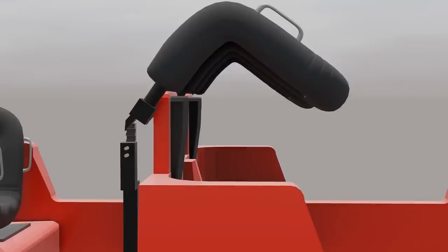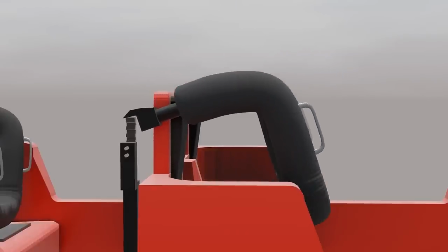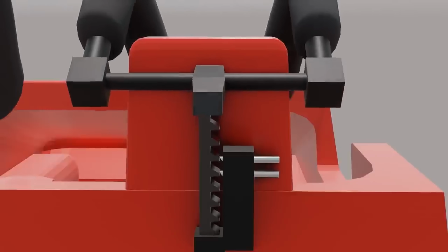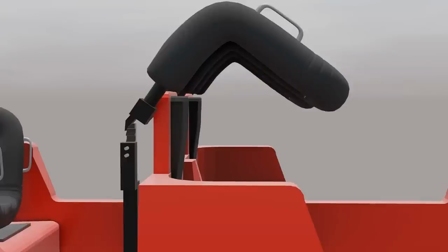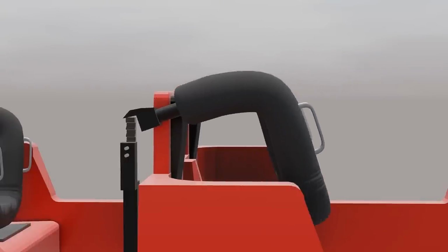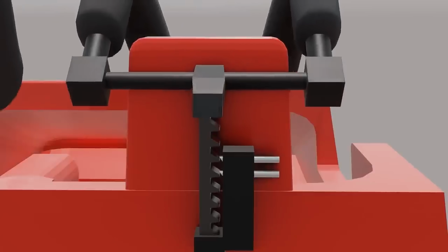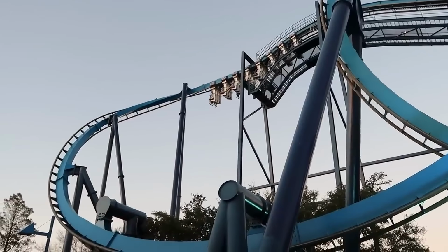A slipped ratchet occurs when the locking pins of the restraint don't fully engage due to being right at the point of engagement. Then, usually after the ride is started, the rider will put some force on their restraint that causes the device to pop up into the next highest setting, making it feel like the restraint has temporarily released. This is more common when the ratchet device gets worn or when there is debris in the device.